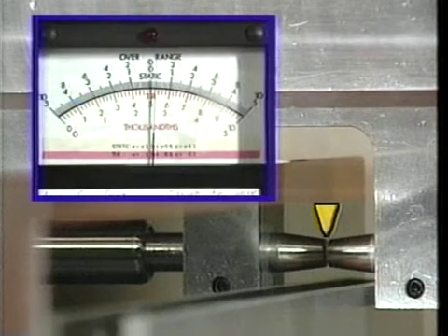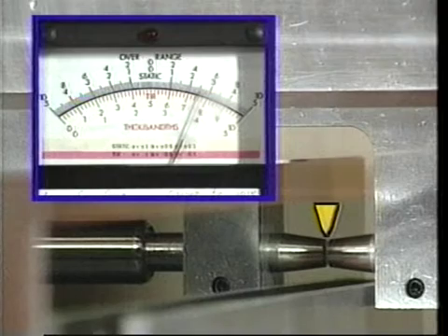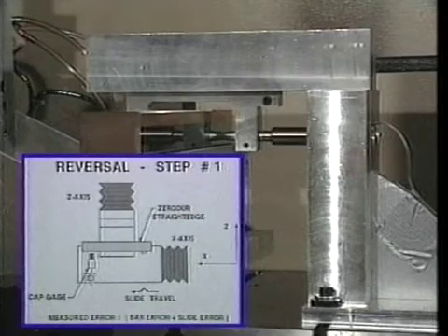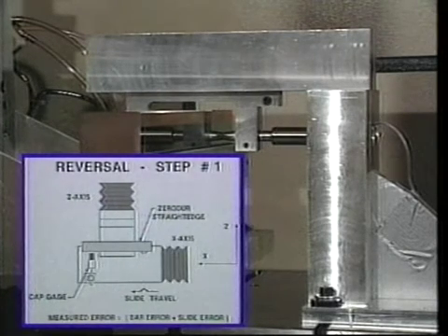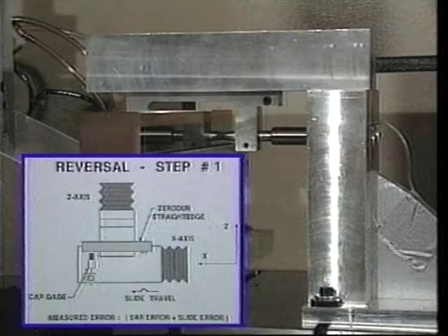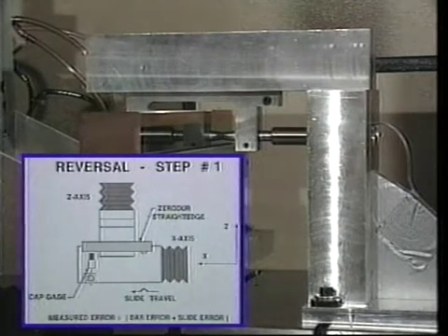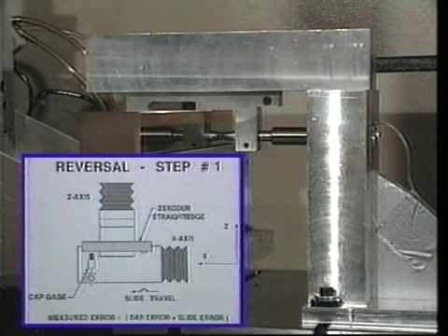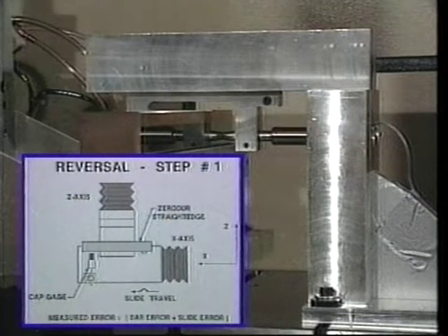A decrease in the separation gap causes an increase in the output voltage, and an increase in the separation gap causes a decrease in the output voltage. In this first configuration, the straightness errors in the slide and the straight edge are additive. Using the reference systems shown, a protrusion out of the reference surface in the negative z direction and the motion of the x-axis slide in the positive z direction both cause the gap to decrease and the signal voltage to increase.